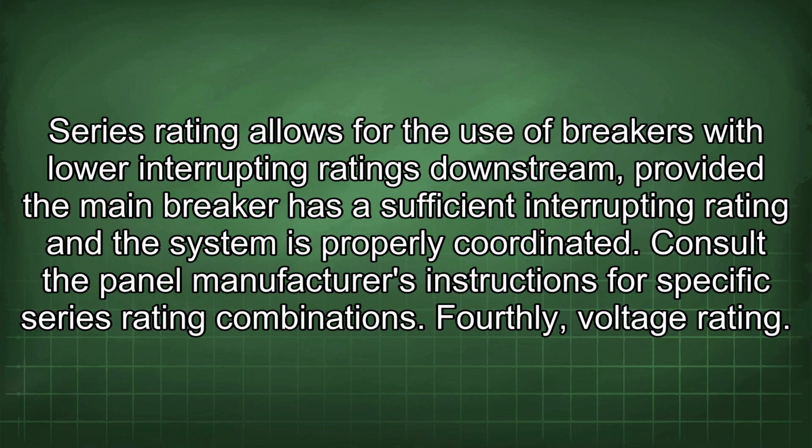Series rating allows for the use of breakers with lower interrupting ratings downstream, provided the main breaker has a sufficient interrupting rating and the system is properly coordinated. Consult the panel manufacturer's instructions for specific series rating combinations.